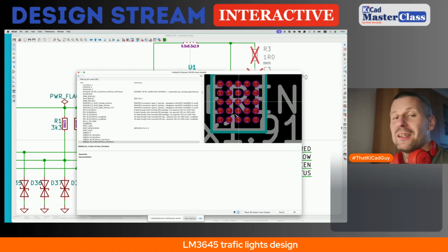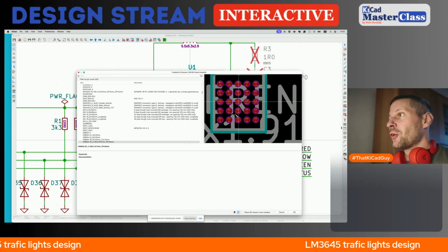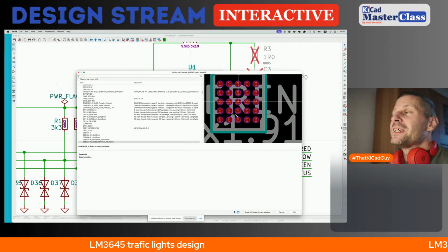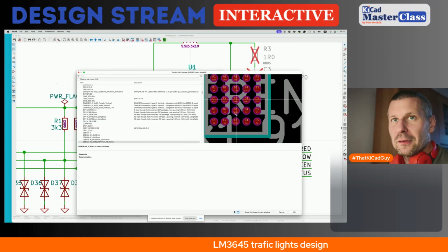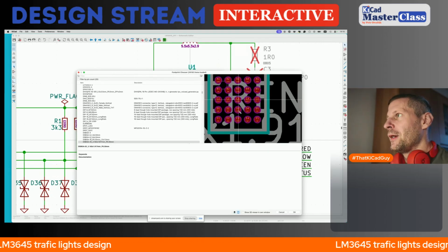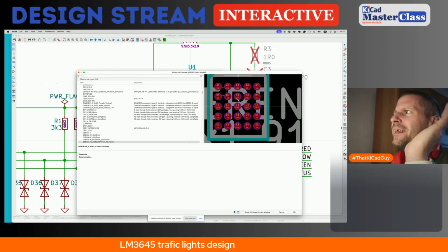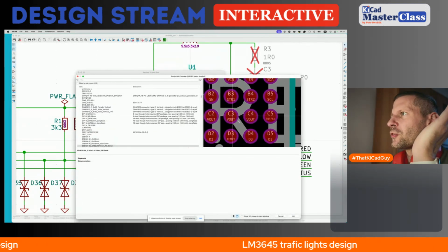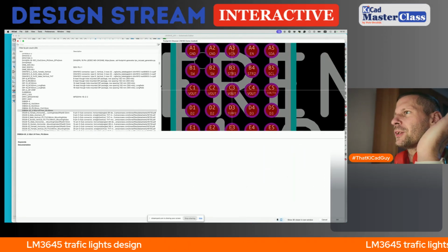But when I started studying the datasheet with the diagram of ports, and when I saw the actual ports, I realized that the pinout of this BGA is so well designed that literally only one pad is difficult to fan out. And this is, frankly, I think three of them, the strobe 1, strobe 2,